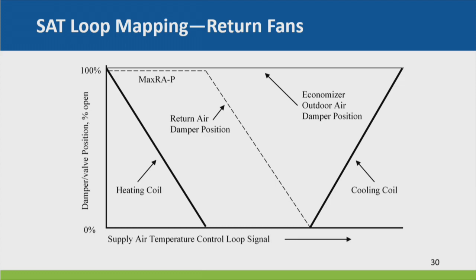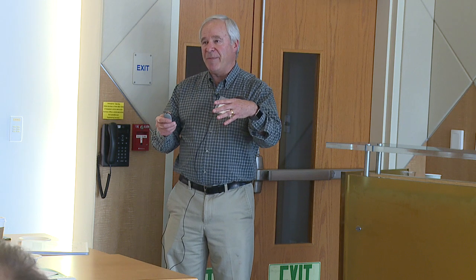We're doing a laboratory right now where the building is about half lab, half office, and we have a return fan, and we don't have any outside air damper at all because it runs 24/7, and the ventilation requirement, because of all the labs and all the 100% outside air stuff, is way more than what the offices need. So I don't even have to measure the outside air. I'm always over-ventilating the building. By using one air handler for both the labs and the offices, I'm actually using the ventilation air from the labs to ventilate the offices for free, so to speak. And the controls are super simple. I have no outside air damper at all, and no airflow measuring station because I know I'm always ventilating more than I need to. So it's quite pretty.